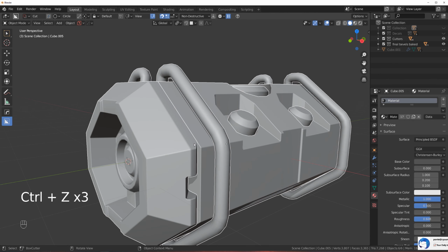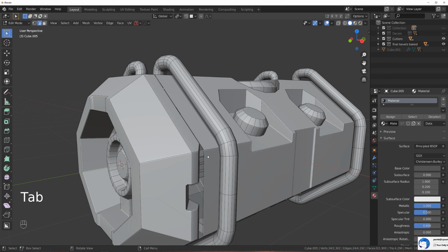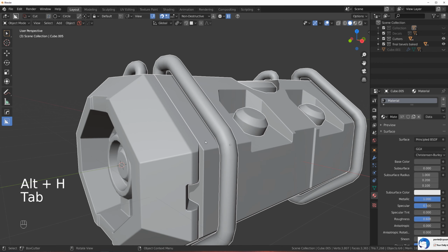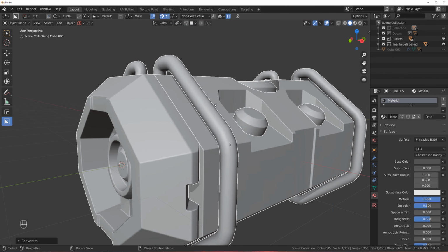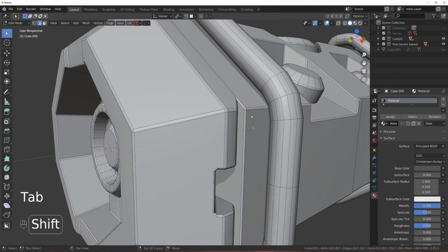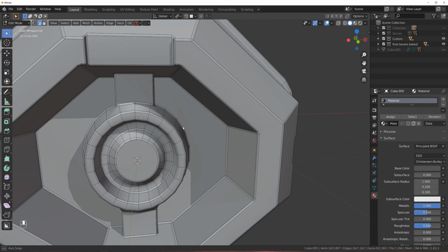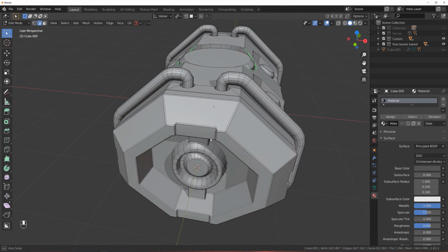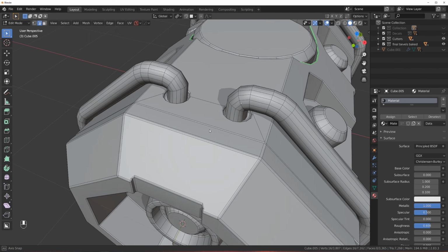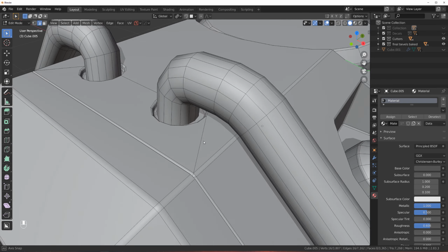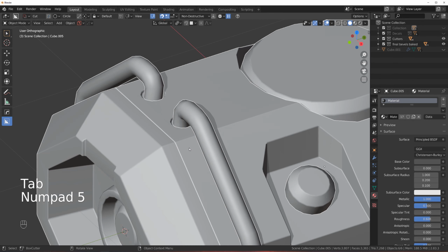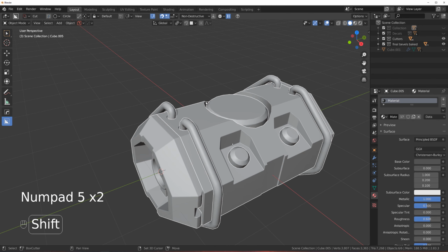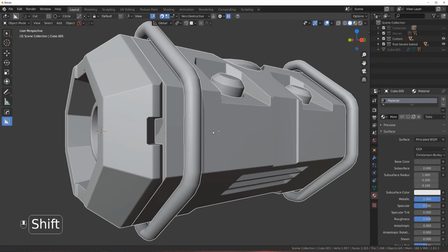And before we do that, let's unhide this face here. There we go. So now visual geometry to mesh, and now we have all the bevels baked, you see. So you could either export it with bevels or without bevels. It's really up to whoever's going to be texturing it. Some people just bake bevels on top of the base mesh, and others export with bevels.